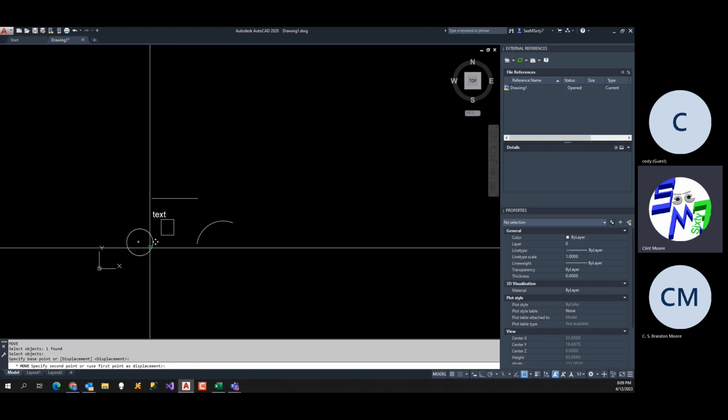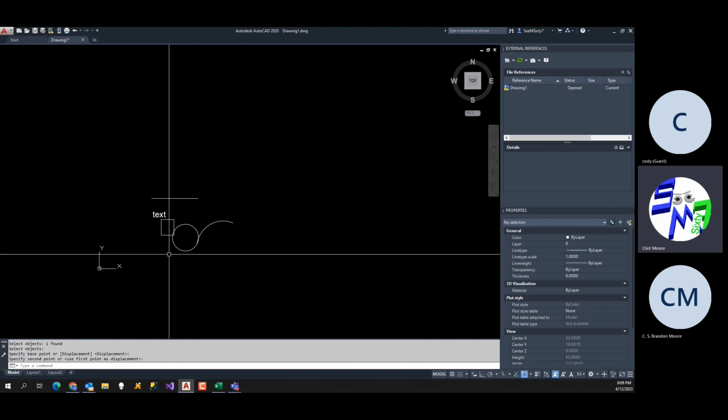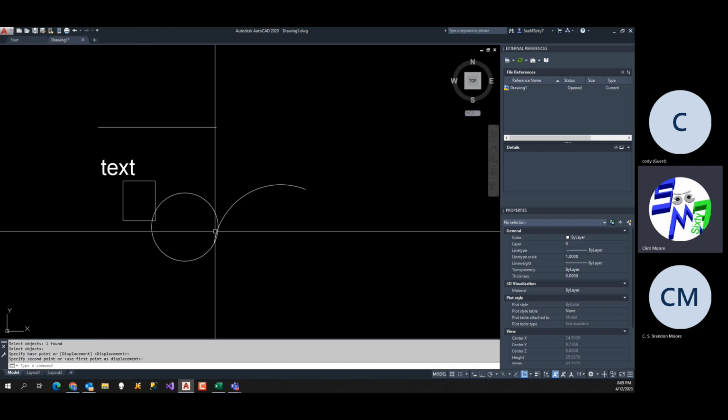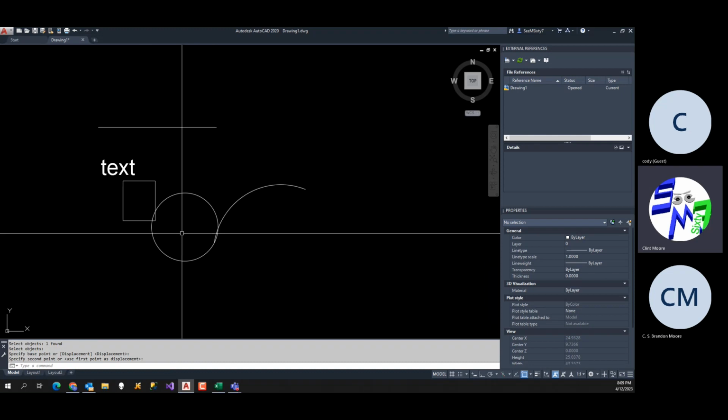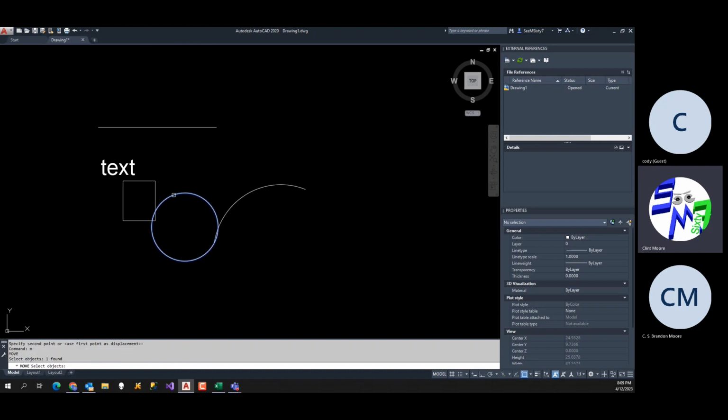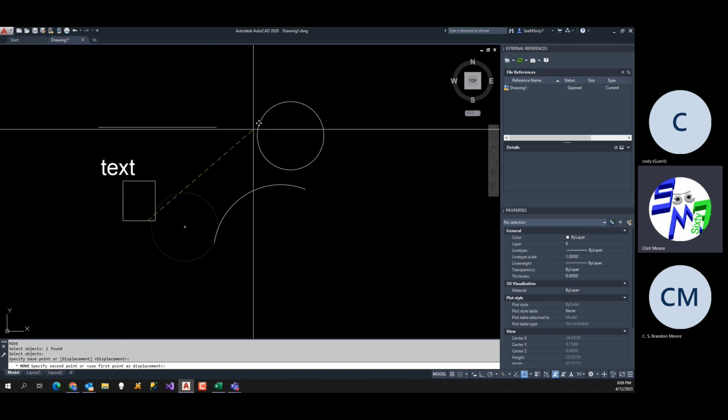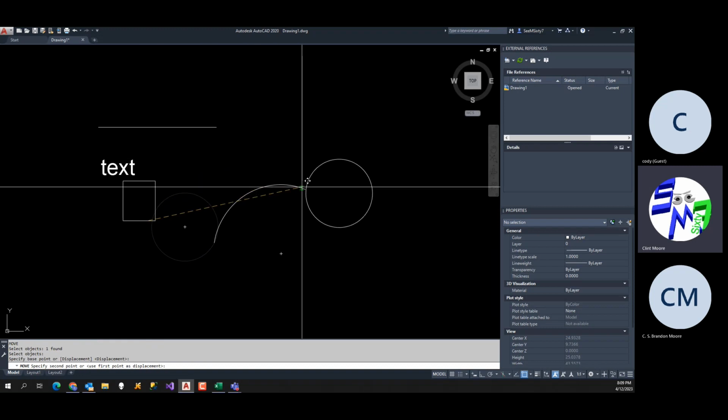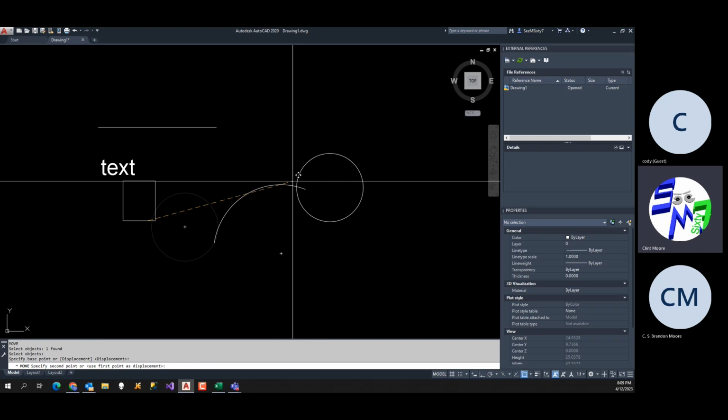So what happens is if I pick here and I drag over here, then it uses those O snaps. And I didn't really want it to do that. I wanted it to actually go somewhere else. So again, if I'm picking here and I do this, then I'm good. But the second I get close to something else, it snaps to one of those points.